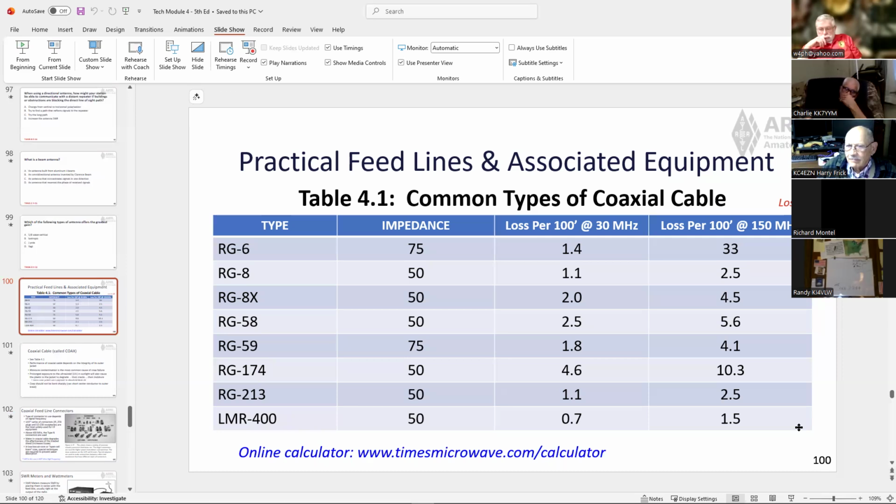So with better antennas, the more gain you get, the more directional they are, which can be an upside and a downside. If you have the room, you can put up a rhombic antenna for HF. You can make it out of just wire and get 20 dB of gain, but it's got to be 1,200 foot long, and you can't turn it. Yeah, there is a price to be paid somewhere.